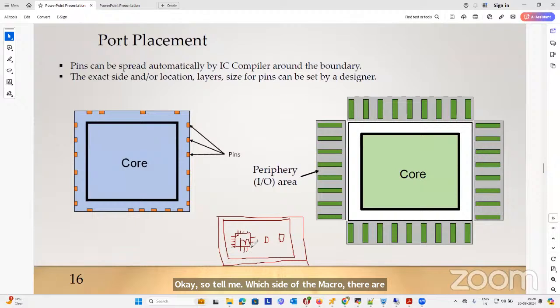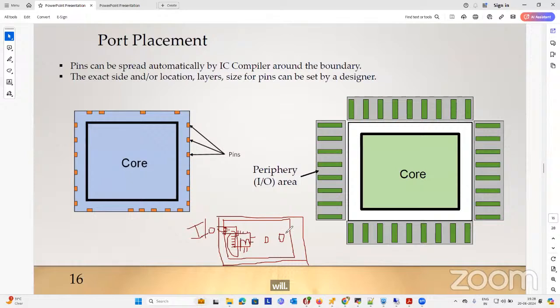That is the higher density of pins. So we will place it towards the corner of the core area, so these pins can get directly connected to the IO port. This is the reason we place the side with more pins towards the IO ring side and the side with fewer pins towards the core side.